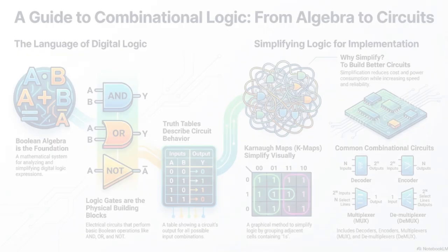And when we talk simplification, the real heavyweights are De Morgan's theorems. Oh, they're essential. Forget the dense math for a second and just think about the idea behind them. De Morgan's theorems basically show this amazing duality between AND and OR. They let you swap the operators so you can turn a bunch of ANDs into ORs as long as you invert the inputs and the output.